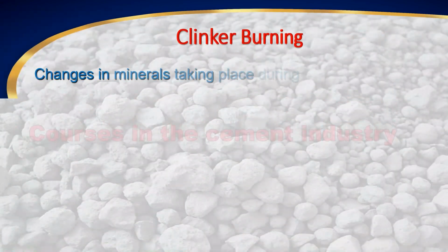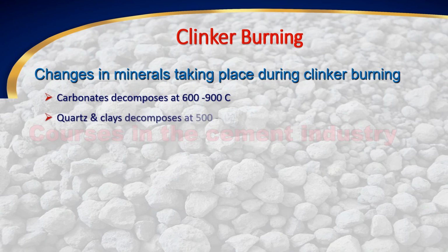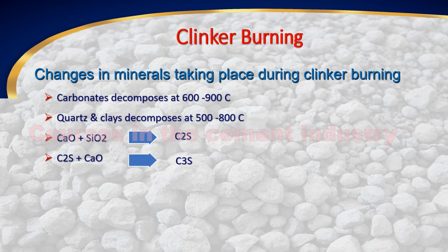Changes in minerals taking place during clinker burning. 1. Carbonates decompose at 600 to 900 degrees. 2. Quartz and clays decompose at 500 to 800 degrees. 3. CaO plus SiO2 equals C2S. 4. C2S plus CaO equals C3S. 5. Al2O3 plus 2CaO equals C3A.